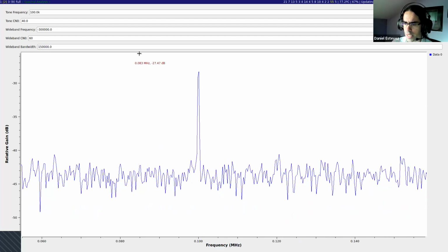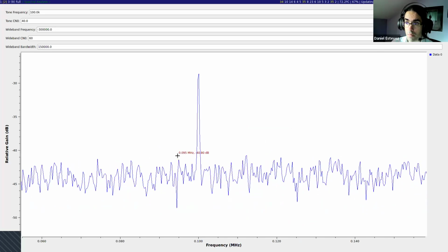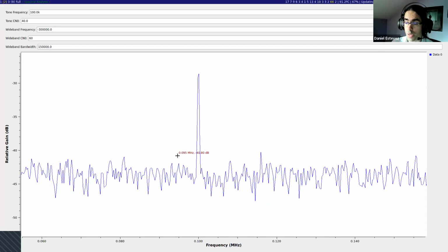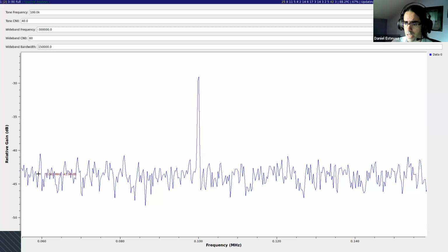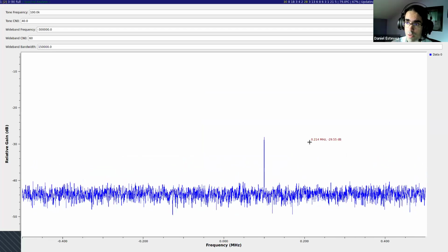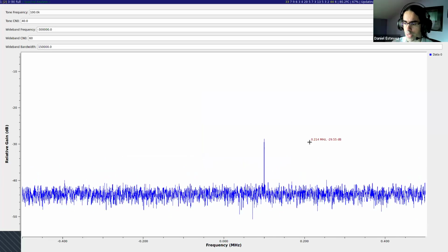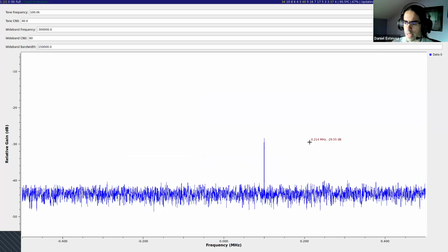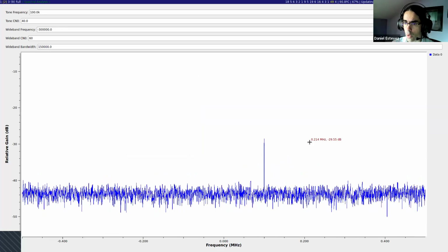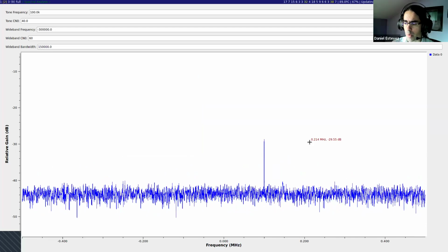Maybe they have selected only this bandwidth and then 1 megahertz is no longer a number that is relevant for the problem. So you always need to keep saying, I'm measuring the noise in 1 megahertz or in whatever bandwidth you are measuring. And for that, there is a common bandwidth for measuring noise that many people use,